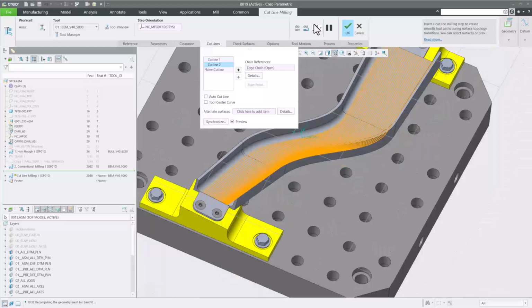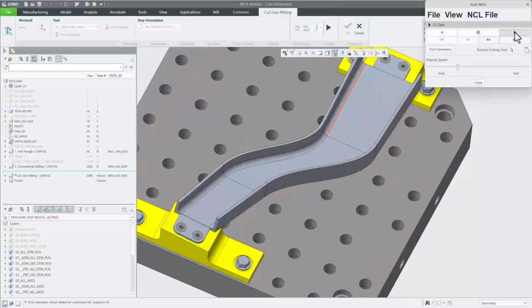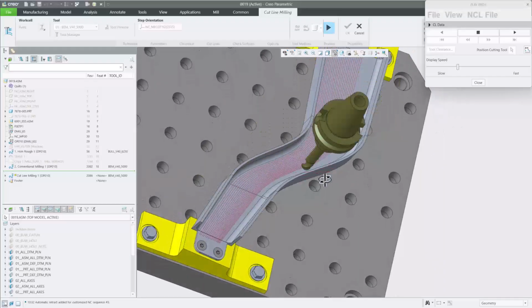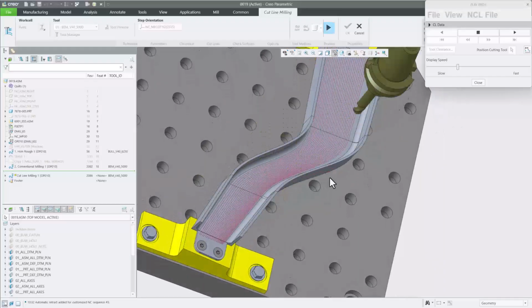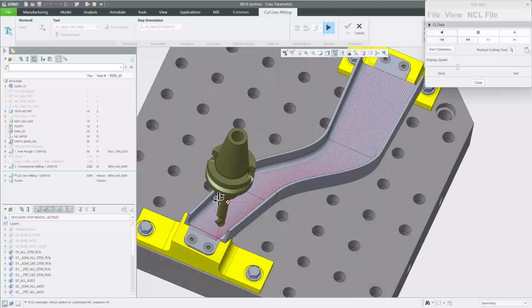And that's quite often a really good toolpath. So if we go play this, you'll see now a much cleaner way of cleaning up all of those. And then it automatically adjusts the step over to get, again, the maximum, whatever you've chosen would be out here, but it automatically brings it closer as needed to do that.